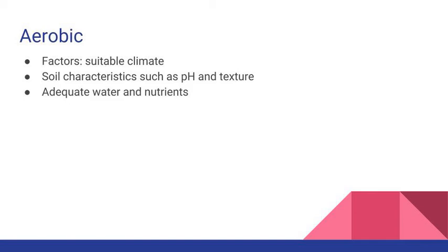Bench and pilot scale studies have demonstrated the effectiveness of anaerobic microbial degradation of nitrotoluenes in soils contaminating municipal wastewater. It is employed where the protection and restoration of the beneficial use of groundwater and drinking water is not primarily the remediation objective, in facilities where chemical and or physical methods, such as pump and treat plants, are not technically or physically feasible.